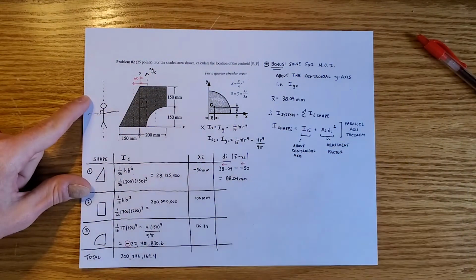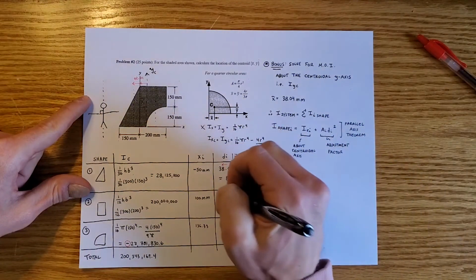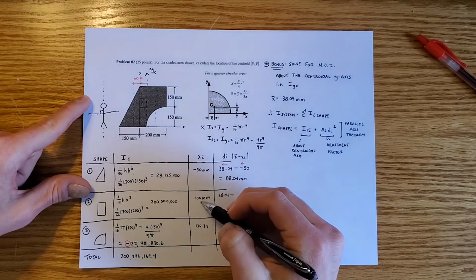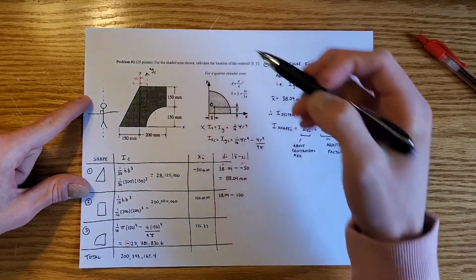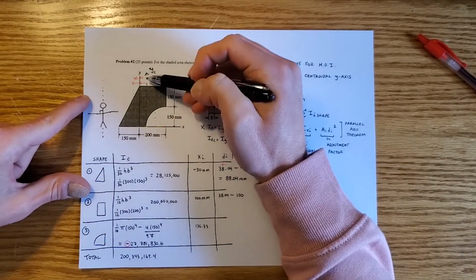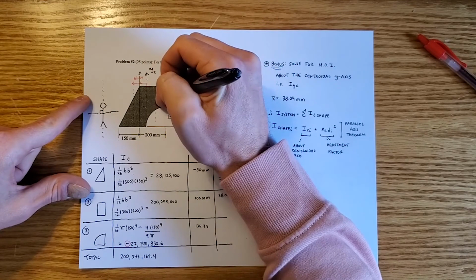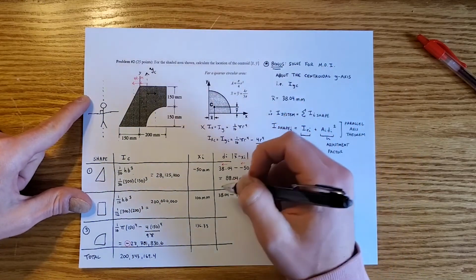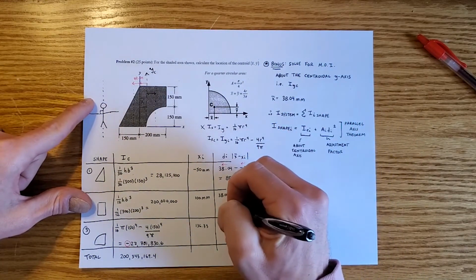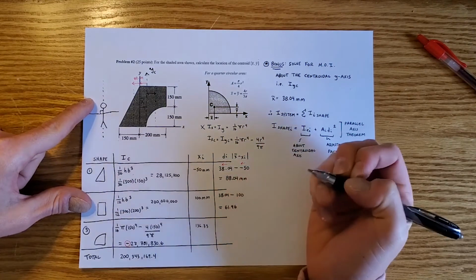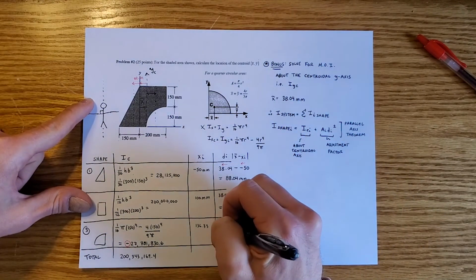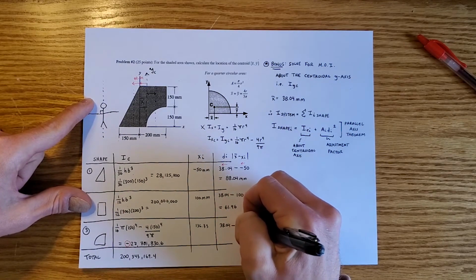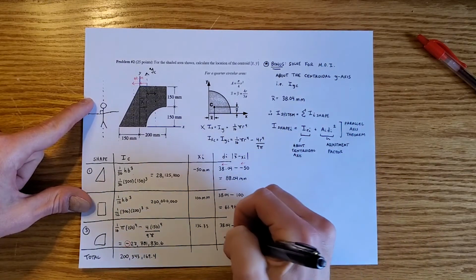We now repeat that process for the rest of our shapes. And we say that di here is 38.04 minus xi, which is 100. So if we look, what we're essentially doing here is that the distance from here to here is this distance. This is our di for the rectangle. So the distance between those two things right there is 61.96. And last but not least, down here we have 38.04 minus 136.33. And down here we get the answer is negative 98.29.